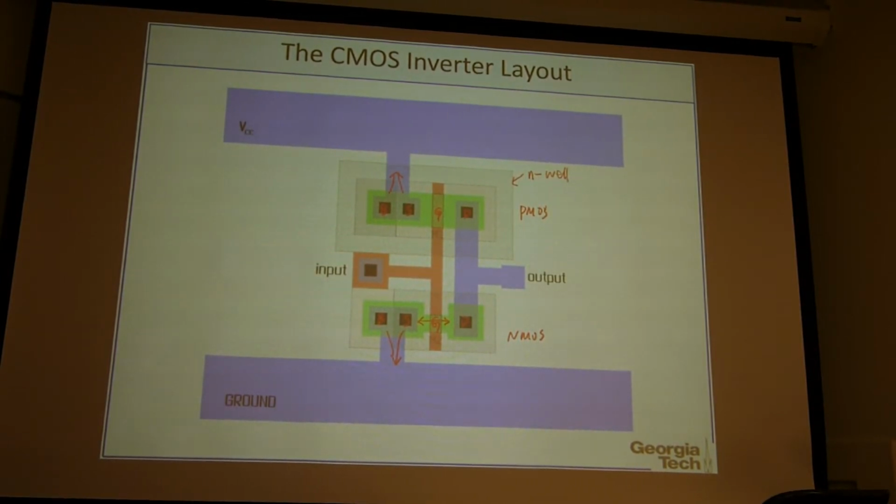And after that, you need to make the contact. That means you are going to make metal wires connecting to your source and drain through that black box, and then later you need to build the power supply and the ground metal wires as interconnect. So it's like a step-by-step definition of the manufacturing process through the layout. The layout defines that geometry information, basically.